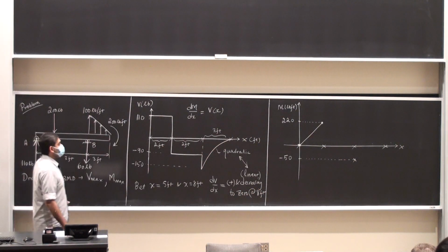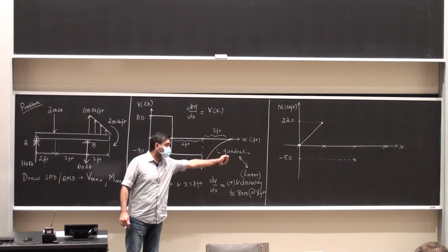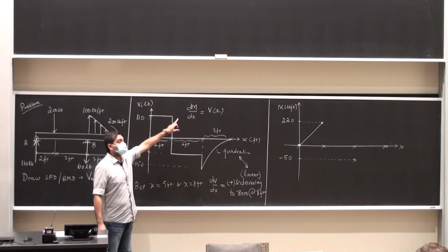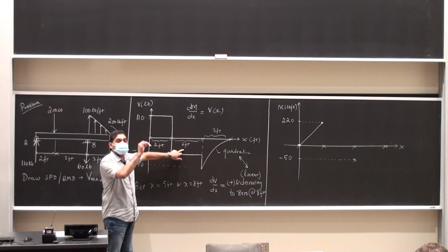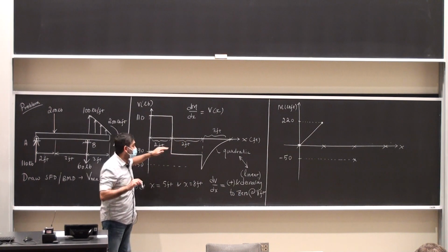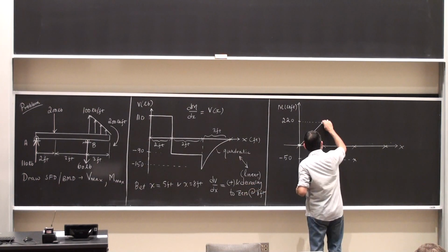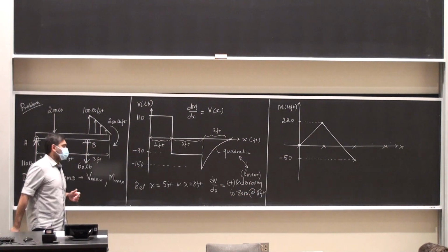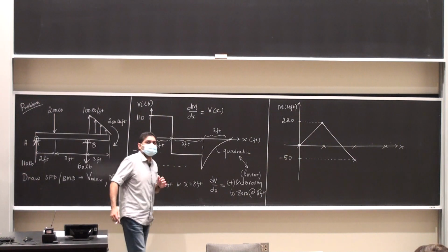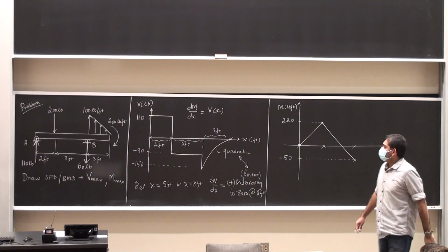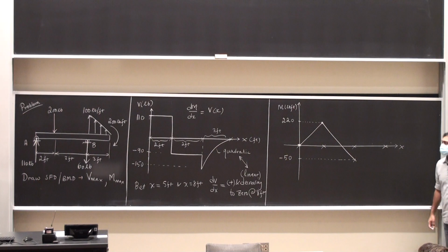How do I go from where I had stopped at 220 pound-feet to minus 50 pound-feet? I look at the slope of the bending moment diagram. It's equal to the value of the shear force, which is negative. So I am descending linearly because the slope is negative and constant. The zero crossing point in a bending moment diagram is of not much consequence to me, so I don't worry about calculating that crossover point. Okay. Questions so far? Everybody on the same page?